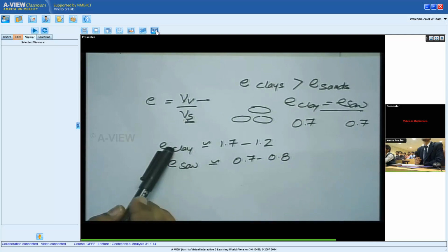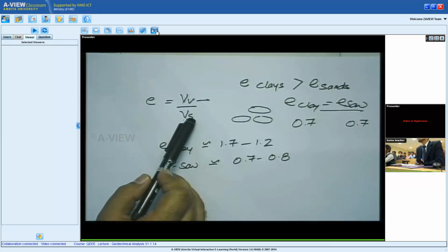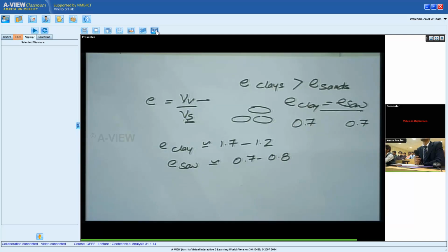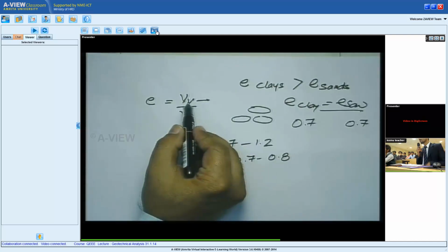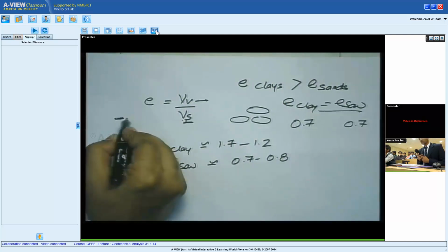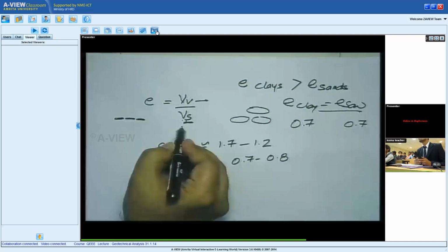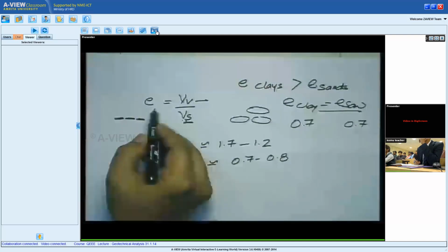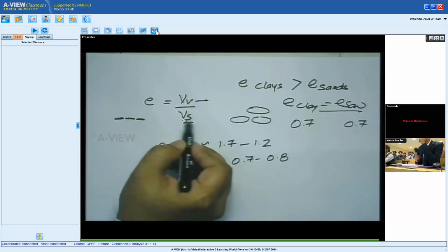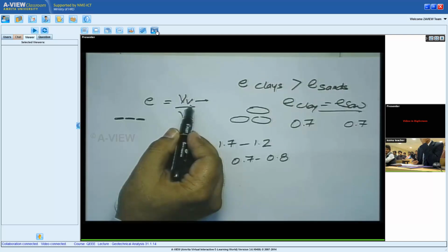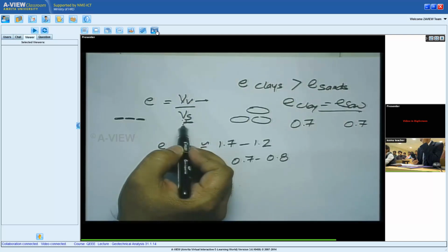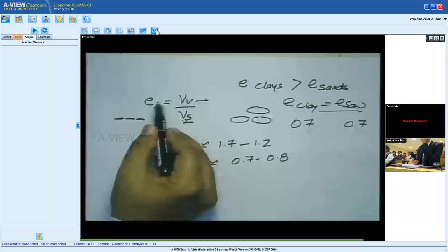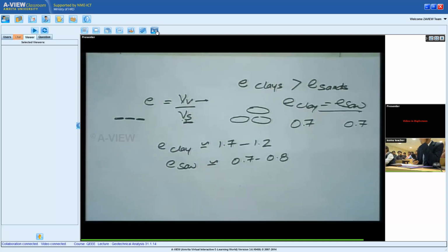So this void ratio has nothing to do with individual volume. Remember, it's a ratio of the two, so you can't take it into individual volume. The clay particles are pretty small, so the volume of solids is small over there, which makes my ratio larger. If I have a denominator which is small, the e value will on its own become large.